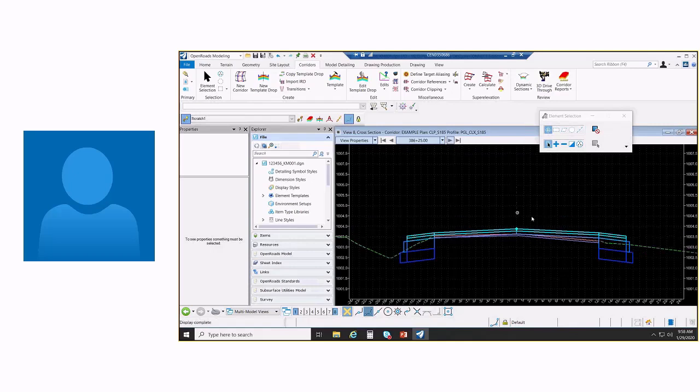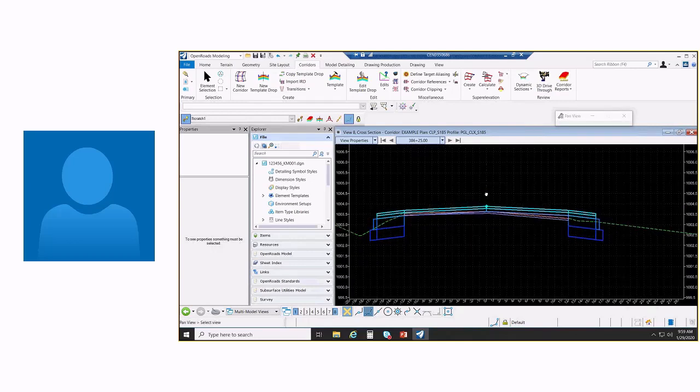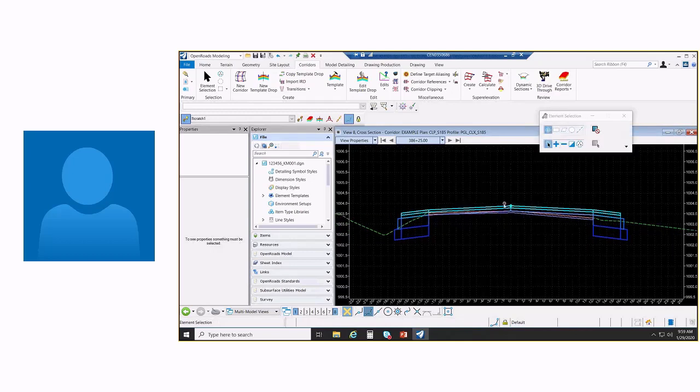All right, so I want to move up somewhere where I'm in full depth. So there's a couple things here. There is a component doing some pavement planing, taking off probably just an inch, and then there's a wedge course component defined in there, and then there's my 2 surface courses, 1 1/4 and 1 3/4 in the template itself. And this is set to use just a 1.6% cross slope. So this would be in the case where I am going out and correcting cross slopes.